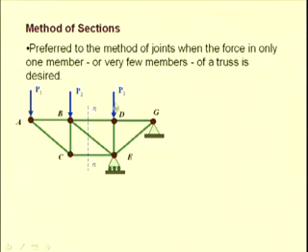But if we use the free body diagram of the portion DEG, then one has to determine the reactive forces at G and the reactive forces at E. But if we consider the free body diagram of the portion ABC, then we do not need to determine either the reactions at E or G. So, let us use the portion ABC to analyze this truss.